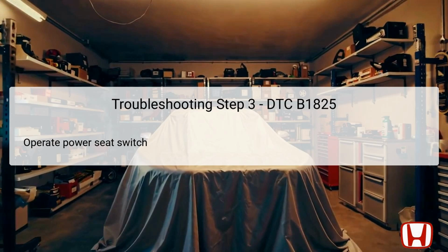For the B1825 code, it is essential to carefully observe the seat transition. If the switch is held longer than 1 second after reaching its limit, this may trigger the code, even if all components are functional. Such testing reinforces understanding of system interactions and ensures fluid movement capability. Document and note responses as you engage the switch to identify if the DTC reappears.